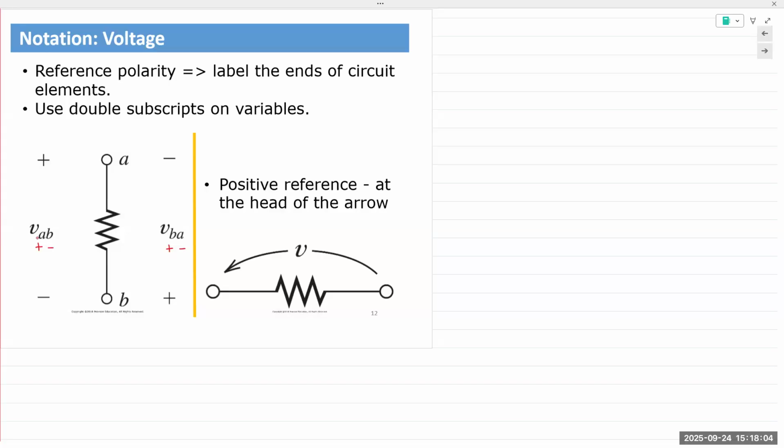Later on in this course, when we get to transistors, and in lab 346, when we look at the BJT experiments, there will be a triple subscript notation, ICBO, ICEO. It's basically collector to base current with the emitter open, and collector to emitter current with the base open. There it's not referring to points, it simply means something else. But if it's a double subscript notation, this is something you should keep in mind.